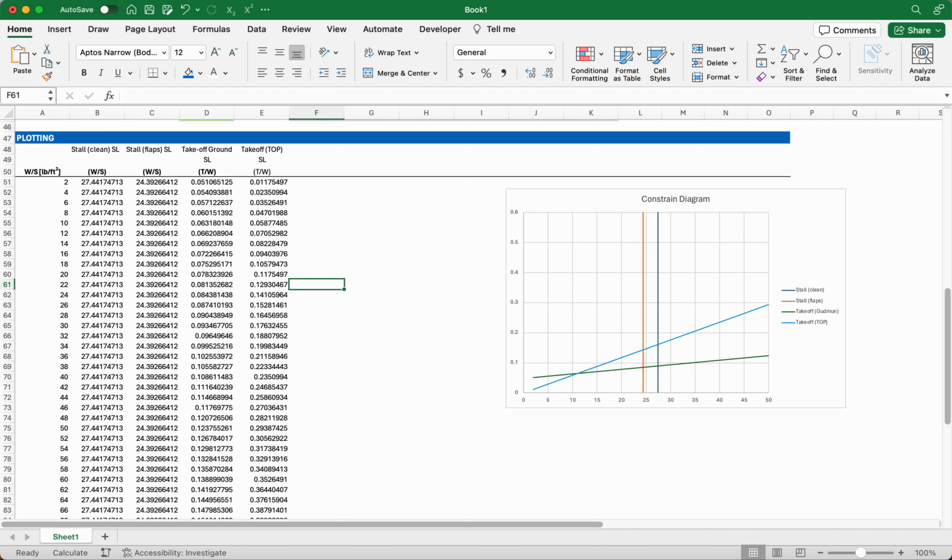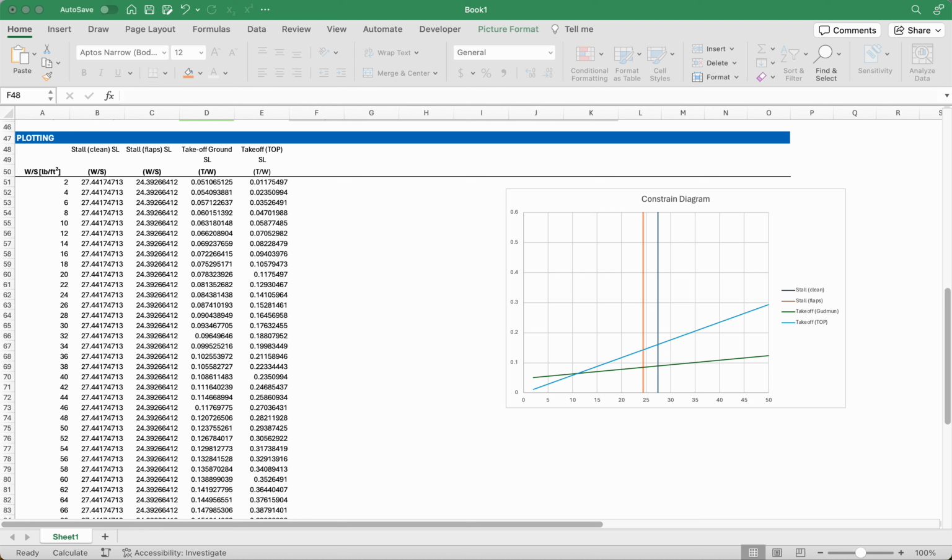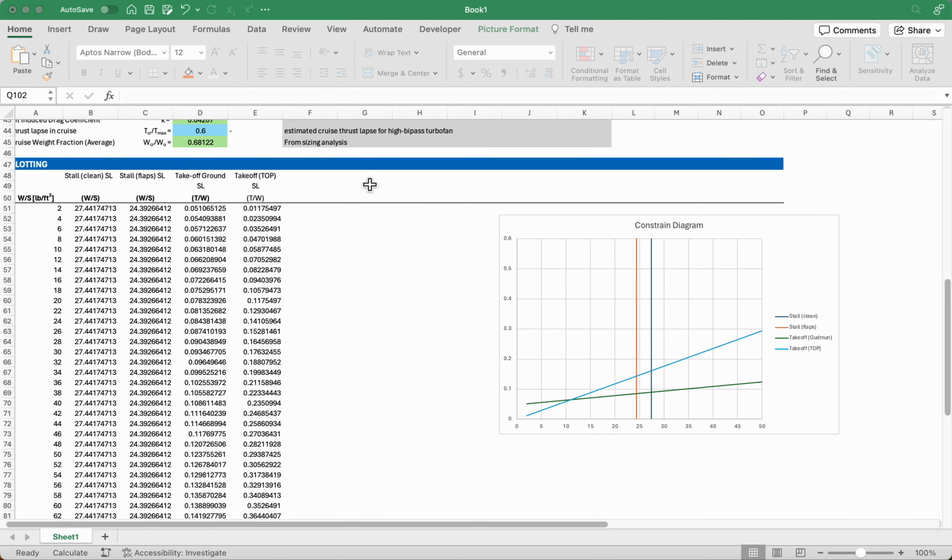So we can estimate the average time to climb to get a rate of climb that we want in feet per minute, which ends up being just over around 1,000 feet per minute for this project. So let's look at climb requirements for best rate of climb and put in this requirement calculation.